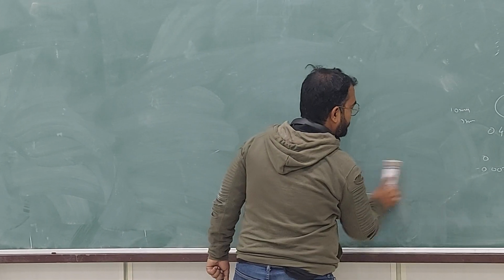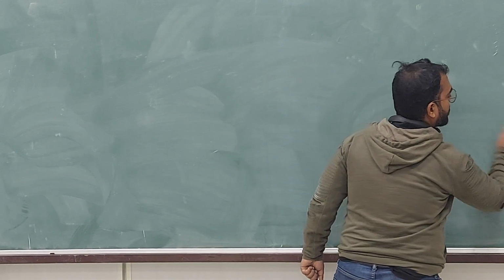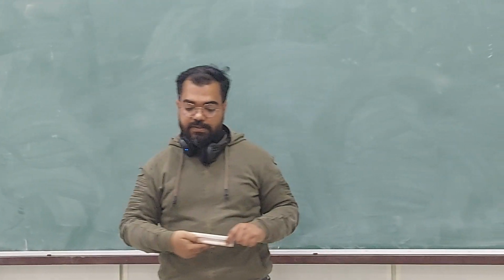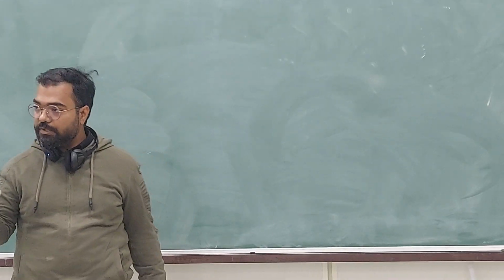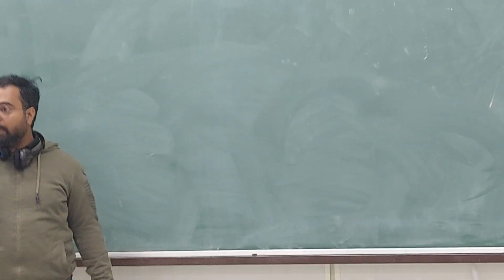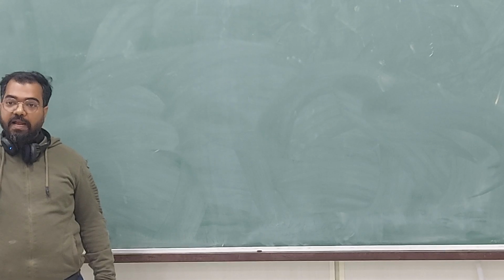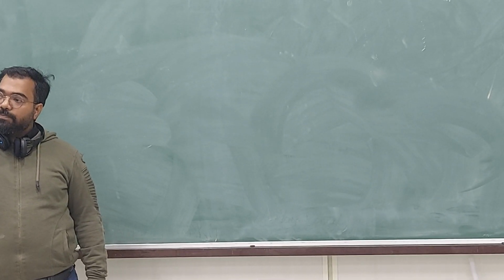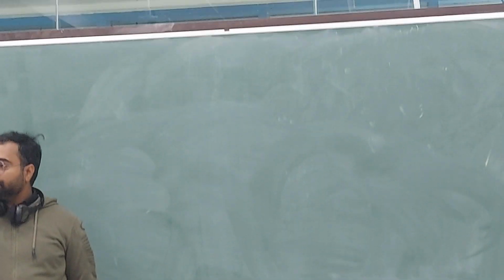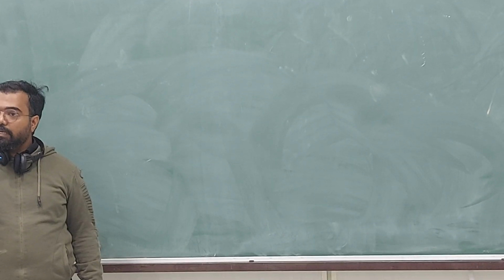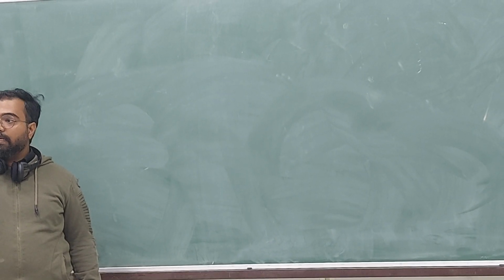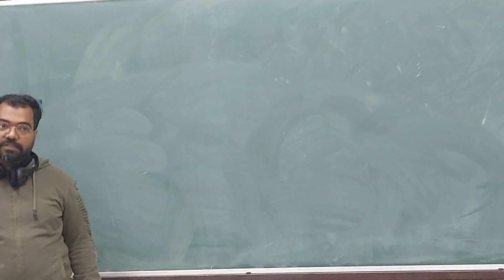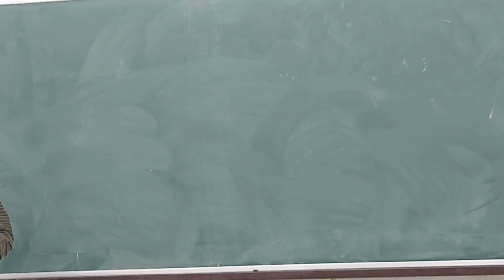Because if the material is brittle, you will not have too much ductile or slow crack growth. You should have flat fracture. Okay? So you should have brittle fracture, with a very small amount of ductile tearing, also known as the stretch zone, which is not really a ductile crack, but the plastic zone which is deformed heavily that appears at the crack tip on the broken sample.